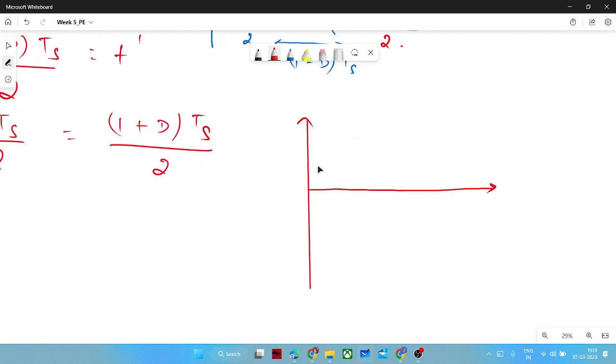Let us assume we have, again, this. Sir, actually we are more concerned about the area here, right? Positive area and the negative area. Once we know that, we don't need to consider the slope, because whatever the slope might be, since the waveform is symmetrical with the horizontal axis, the positive and negative area will be equal. So we don't need to be concerned with this slope.